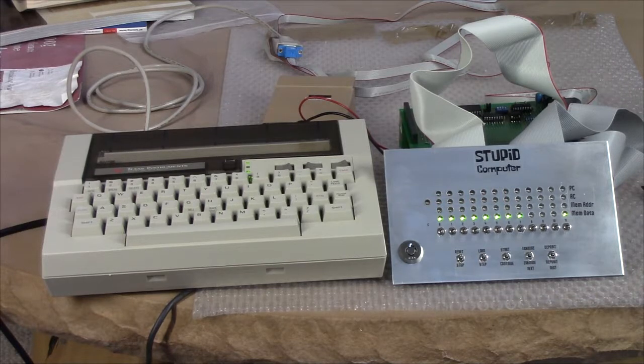I'm using, as you may recall, if you've watched the earlier videos, 74F670s because I found some. And I said, these would be neat to use. Let me see what I can do with them. It's a register file for 4 registers. However, it turns out they're implemented as transparent latches, not as edge-triggered D flip-flops, for instance.